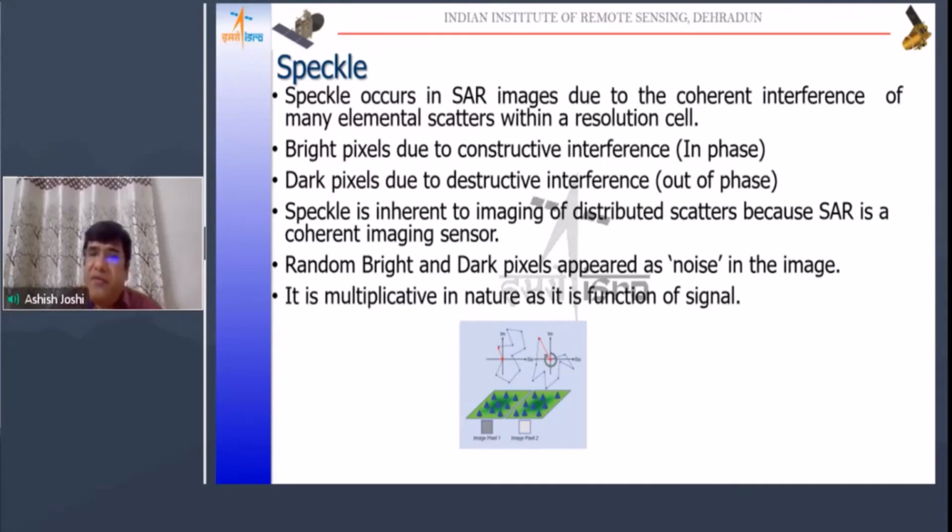After that, we used the SAR and range Doppler equations to convert the SAR slant range image to the proper ground range image or proper geocoded image using either the ellipsoid correction or the terrain correction. So that is all the geometrical part, meaning we are correcting the layover and foreshortening geometrically.